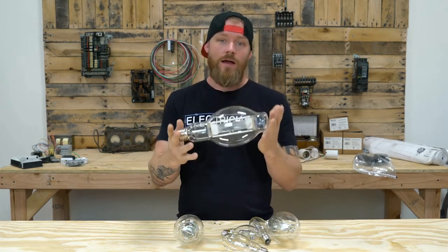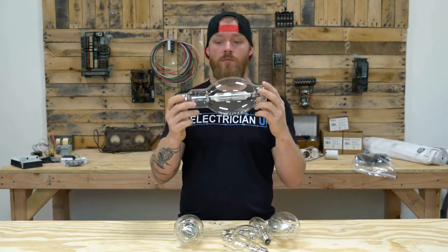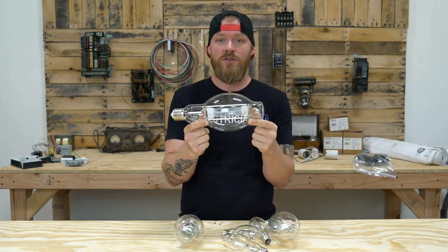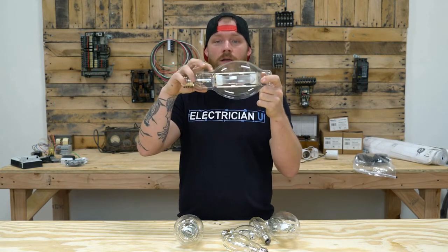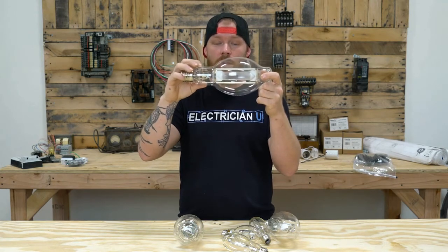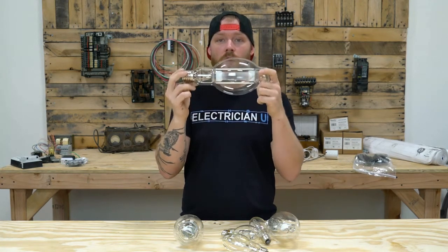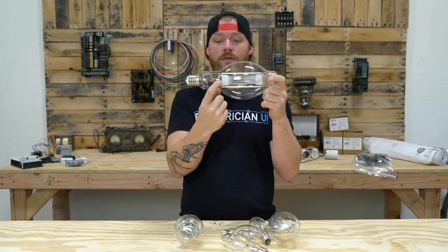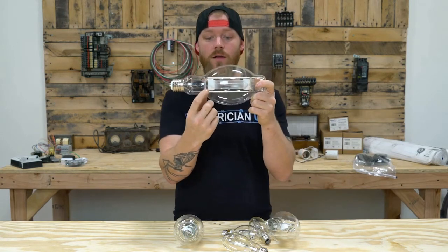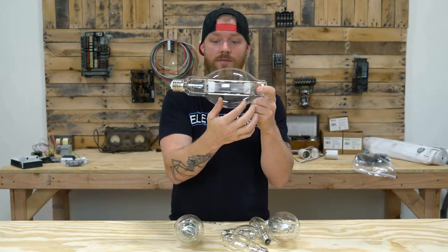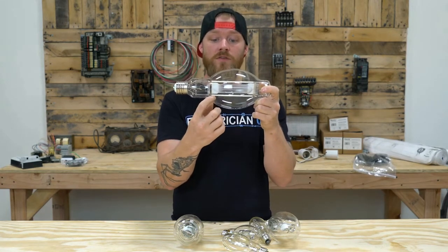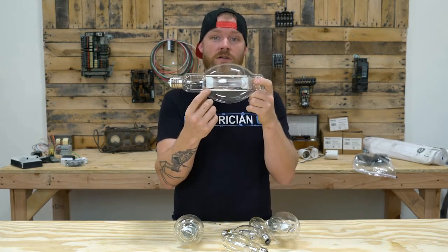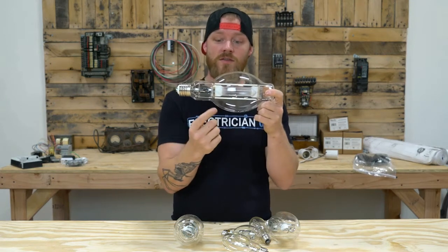Essentially how an HID probe start bulb works is you've got electrodes, one on each side. Those electrodes are essentially just filaments, and then you have a starting probe as well, and that starting probe has a starting resistor. When current starts to go through this lamp, inside of the bottom of it you have this little arc that happens, and that arc will ignite the argon gas on the inside of this, and it starts to heat up to a point where there's a small trace amount of mercury inside of here, just like a fluorescent bulb would have. But that mercury starts to vaporize and create an arc all the way across this tube from one electrode to the other electrode.